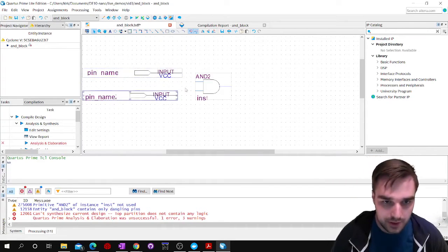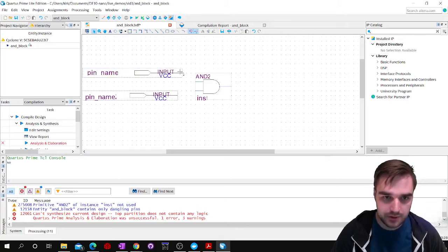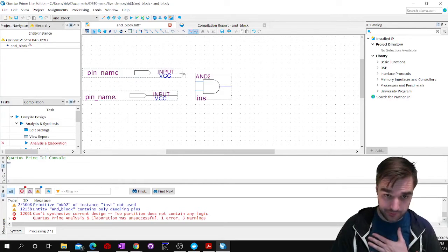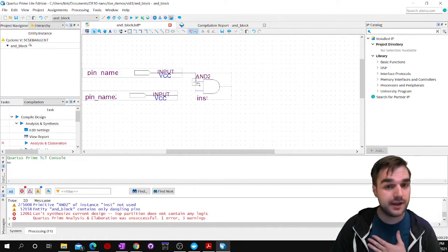So you'll notice these aren't actually connected to each other, but I can click and, oh, sorry. So if I hover over the tip of this wire right here, you see my cursor has that little line with the two dots. If I click and drag, I can pull out a wire, and then I want to connect it to here, and you see that it draws that box around my crosshair. That means it will connect, but I don't like to draw my wires like that.